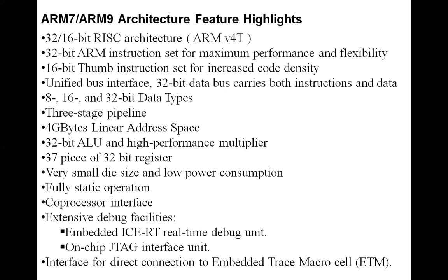It has a dedicated instruction set also, so a separate 16-bit Thumb instruction set is provided. Those programmers who are very familiar with 16-bit code write their programs in 16-bit using Thumb instructions, and those who are aware of the 32-bit instruction set utilize that instruction set.